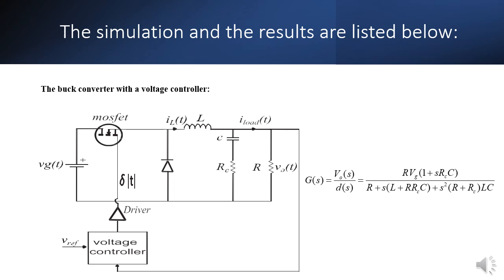Before the transistor turns on, if the inductor current drops to zero, it stays there until the transistor turns on. This is due to the diode's restriction on the direction of current flow. The converter runs in discontinuous conduction mode in this situation. On the other hand, the converter works in continuous conduction mode if the inductor current never reaches zero during any part of the switching period and continues to flow.